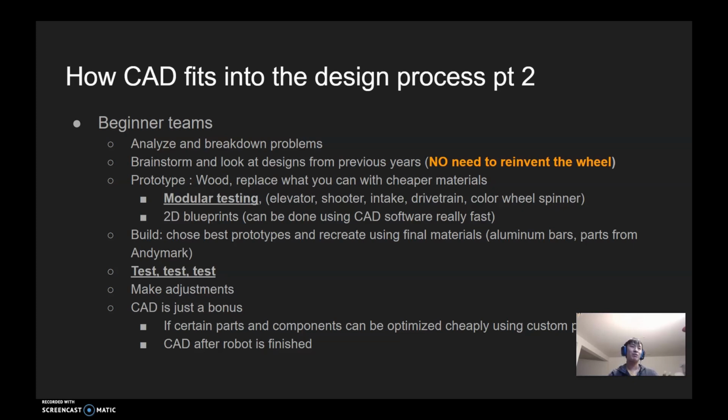Okay, actually, let me start from the beginning again. Modular testing: you want to test every component of the robot separately. You can use stuff to help you emulate the robot and how the actual component will fit into the final robot, but you want to test everything separately.